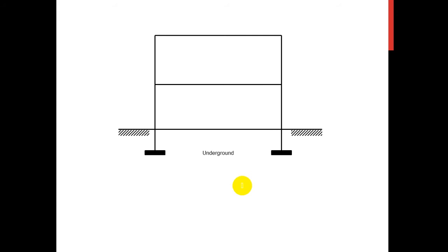To make things clear, let's do this example. Now this example is to assess the nominal cover for durability only. Bond is not included. Suppose I want to design the nominal cover for this interior beam. Let's assume the exposure class or the subclass to be XC1.